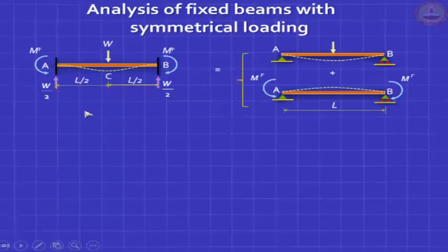Let us see. Well, you could make your life easy by going back to the simply supported beam and saying that whatever I get here is a superposition of the effects caused by the external load W and these redundant moments MF. Okay, this is how statically indeterminate beams are understood. This will make it go down, this will make it hog and go up. And the net deflection here is this minus this. We know that.